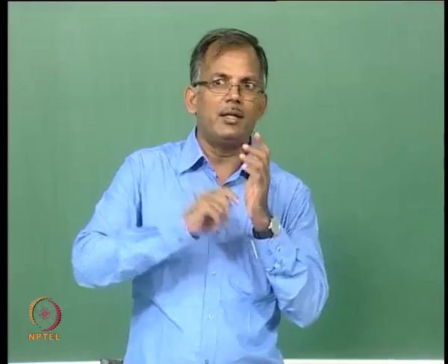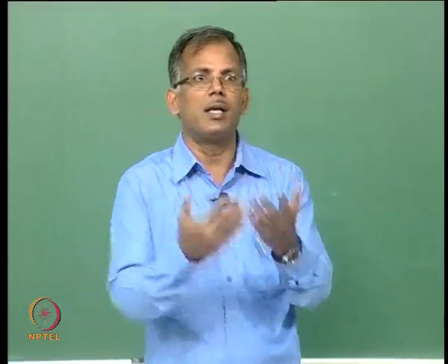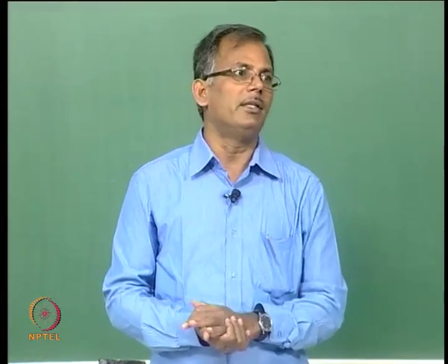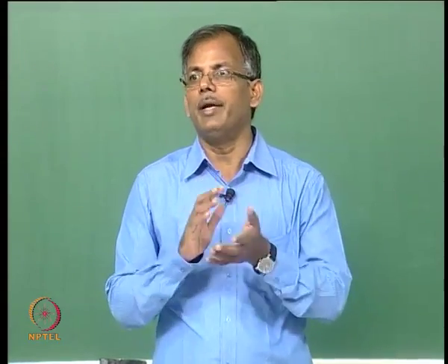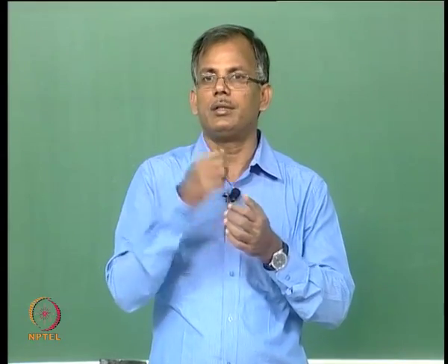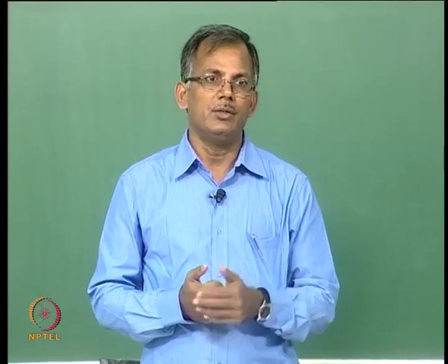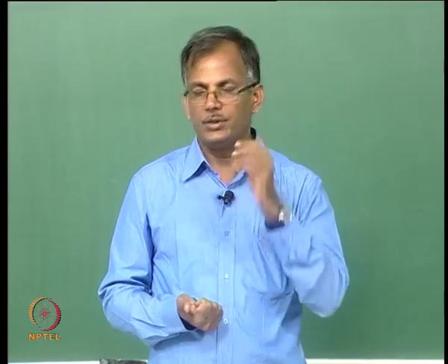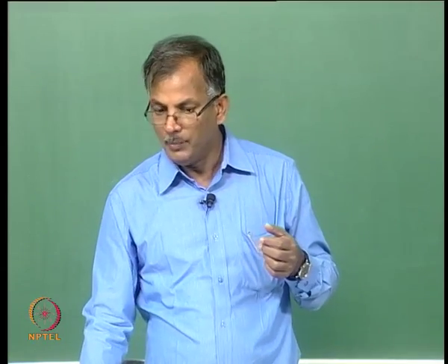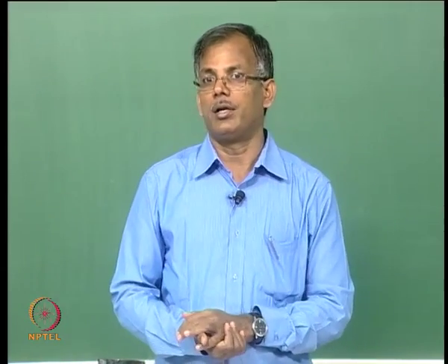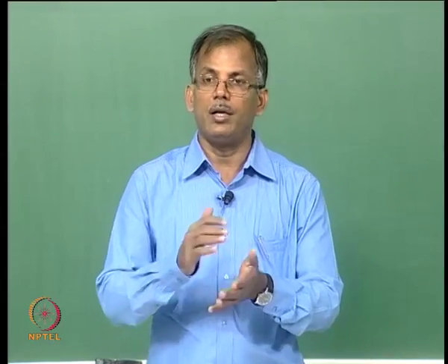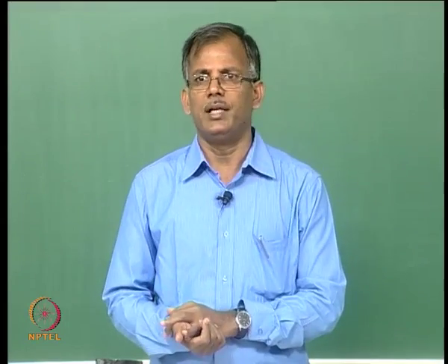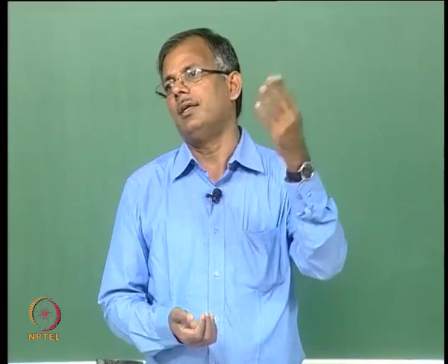So, should we do a linear or should we do a non-linear? The answer lies in the margin that you want to leave. Basically 50%, do you want to leave that? It may be too much. So, that is why you need not conclude on the basis of simplicity, you should see what is the strength you are losing. In many cases it may not be like this, only foundation where you are looking at linear to non-linear, you get so much extra capacity. In other engineering materials you may get only 5% when you go to non-linear.